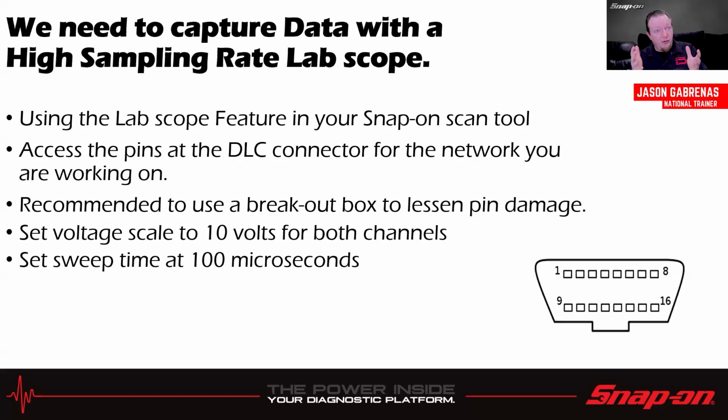So like I said, refer to a wiring diagram when in doubt and make sure you're putting it on the right pins. It's recommended to use a breakout box to lessen pin damage. You don't want to front probe, and it's usually hard to back probe, so we're just going to use a breakout box. I'll show you one in a second.